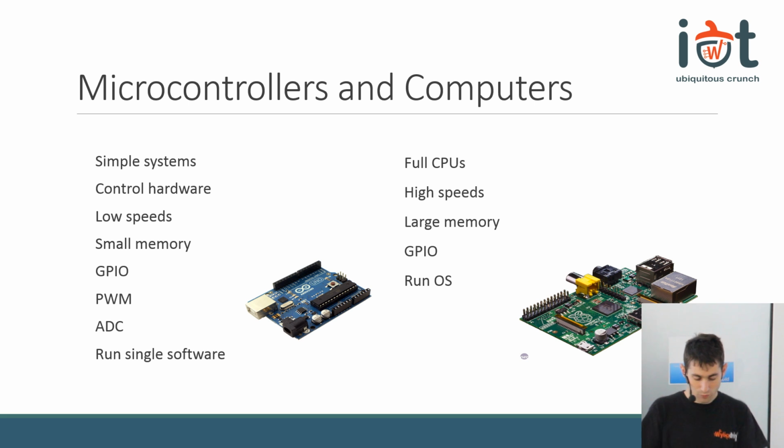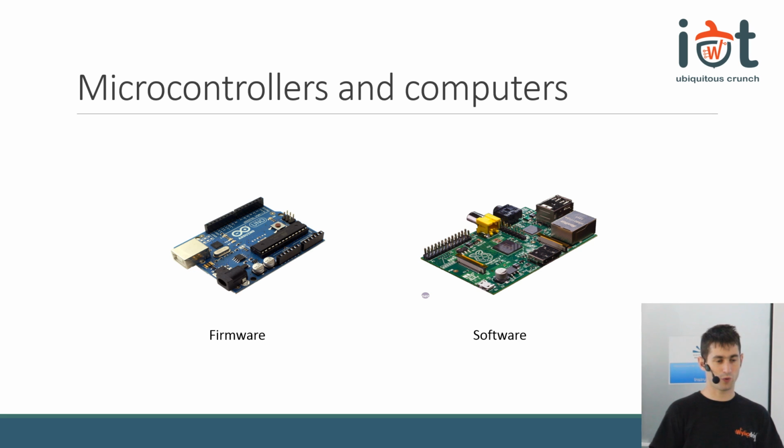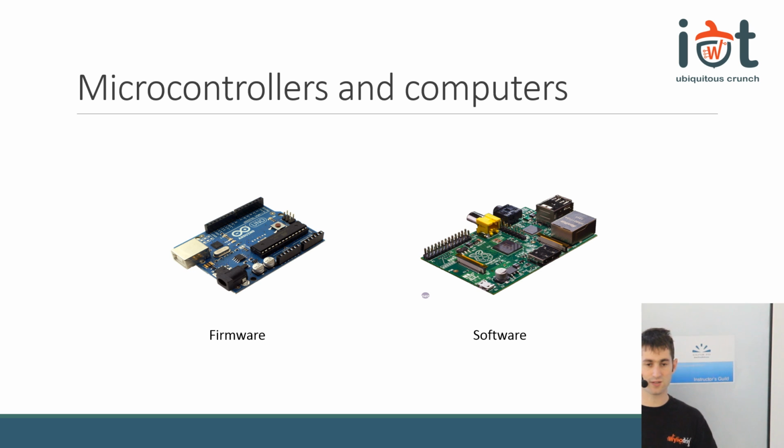Going to electronics. In most of the cases, you will have an embedded device which is going to process, and you will connect sensors to it. Sensors and peripherals. As the device is really bad in talking directly to hardware, you will need some kind of microcontroller on the way. And usually, sensors, which are more expensive, come with the microcontroller inside. If you use Arduino to connect some sensors to the Raspberry Pi, for instance, you are actually building a more intelligent sensor with the Arduino, which you connect then to the Raspberry Pi. Is this clear? So please understand that we are talking about firmware when we talk about microcontrollers, and we talk about software when we talk about computers. So from now on, we will refer as firmware to the programs that we write for microcontrollers, and software for the programs that we write for computers. Is this clear?